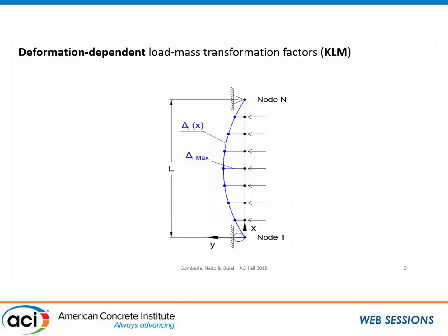The other big thing here that we've touched on is, for those of you that do single degree of freedom work, you're aware of KLM or shape function type analyses, things like that. For simply supported wall panels right now, it's pretty standard, 0.78 elastic and 0.66 plastic, but we looked at it and said, because we're developing the performance-based resistance function, how can we look at how KLM also varies?